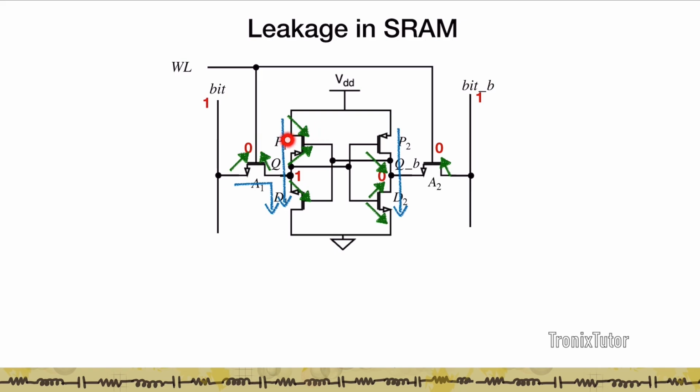Now, with the use of high K, the amount of gate leakage is reduced, but remember that as you use the SRAM, BTI kicks in and that ends up creating slightly higher levels of gate leakage in your system. And so we need to account for all leakage mechanisms that are possible in the SRAM.